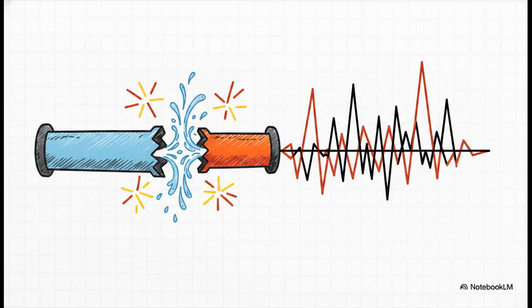Now let me tell you, the stakes for getting this roadmap right are incredibly high. In a multi-loop control scheme, if you pair the wrong controlled variable with the wrong manipulated variable, well, the results are pretty disastrous. Get those pairings wrong, and you've inadvertently engineered your own failure. You just threw away your system stability margins, which leads to wild oscillations and poor control performance. It completely defeats the entire purpose of your multi-million-dollar plant.